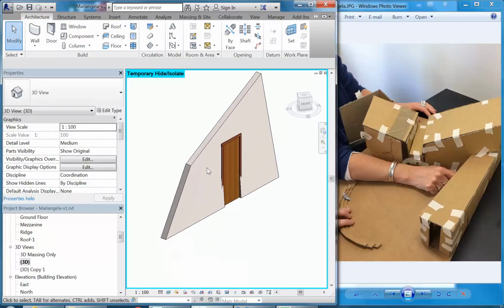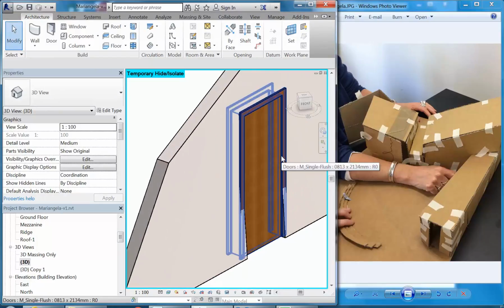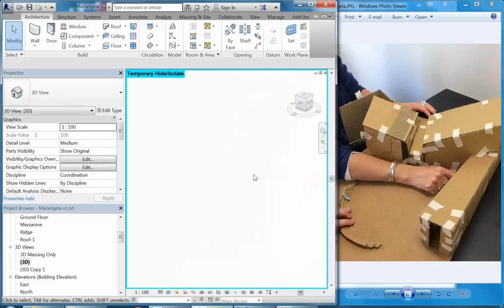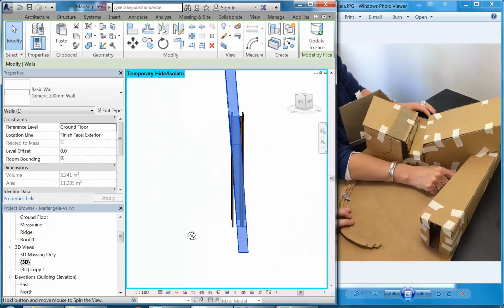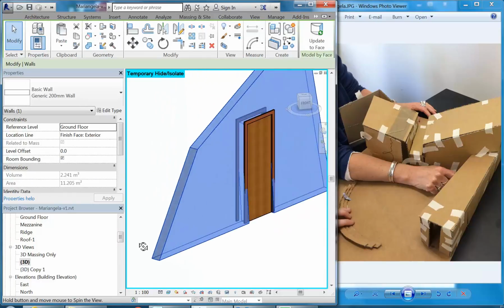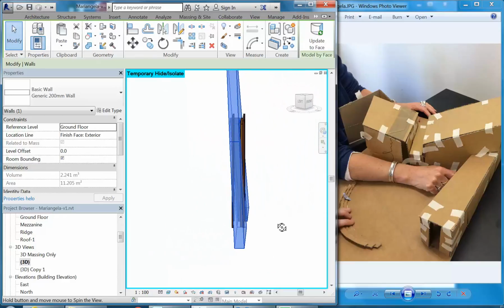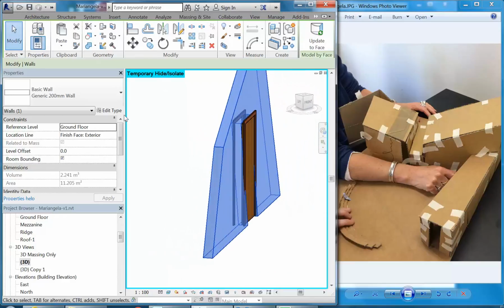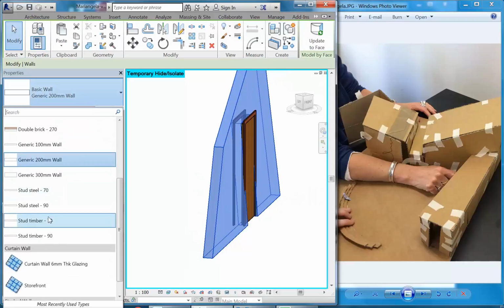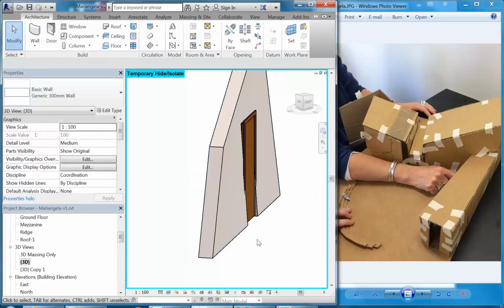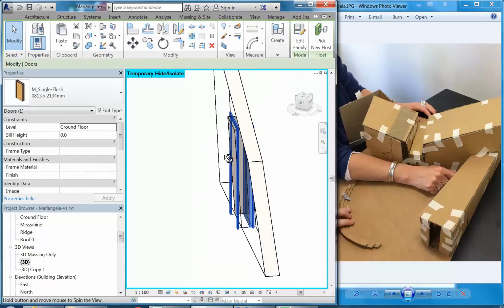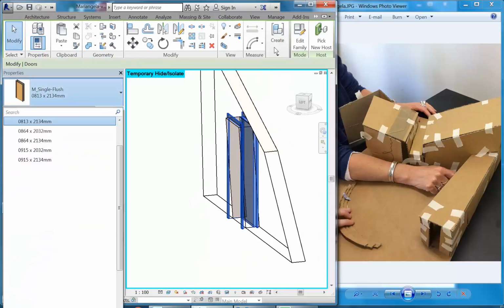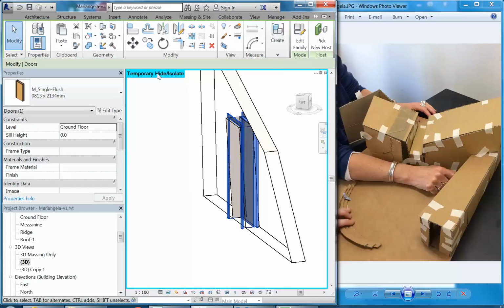Okay, so obviously when you have sloping geometry, you need to work out how your openings are going to interact with that. Openings generally are perpendicular to the ground, so you will have issues, and the usual problem is the depth of the wall. You might need to make it a lot greater than you might have originally, and that will often give you enough. Oh, of course, yeah.